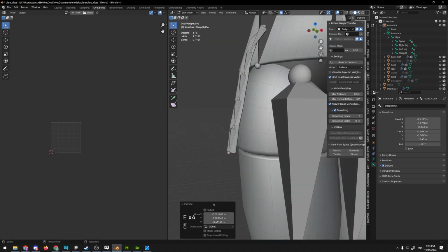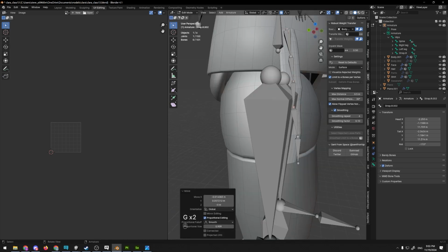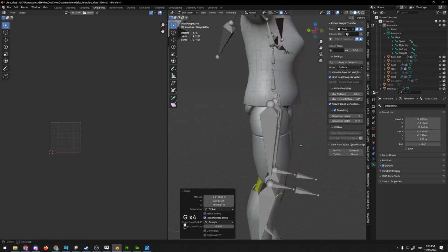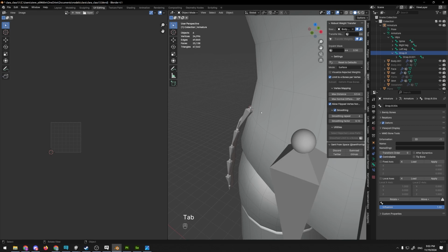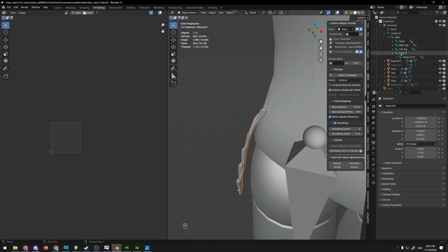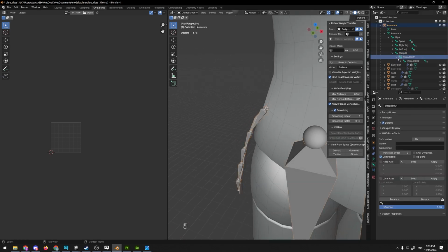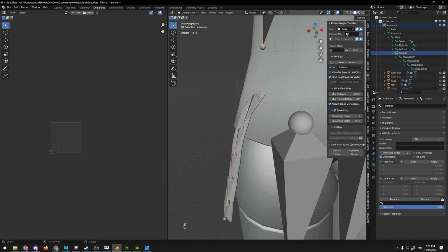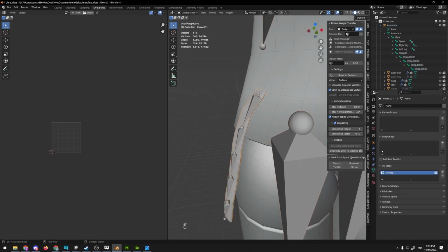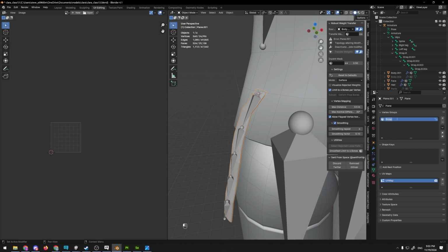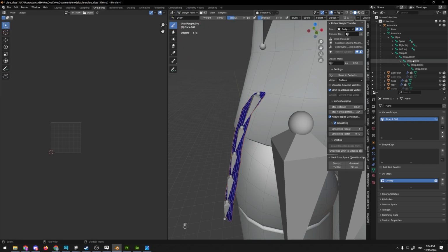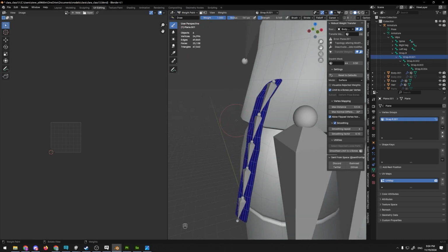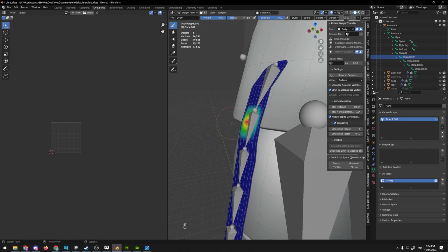So I'm going to re-extrude these bones like I did before. The leg bones being in front is not ideal. Cool. There we are. Now, to actually start weight painting this, we could do this manually. Now that we have strap.R.001, strap.R.002, etc., you could go over to our vertex groups, add a new vertex group, call it strap.r.001, go over to your weight painting tab, find that bone and start painting, right? Add some weight and start drawing.